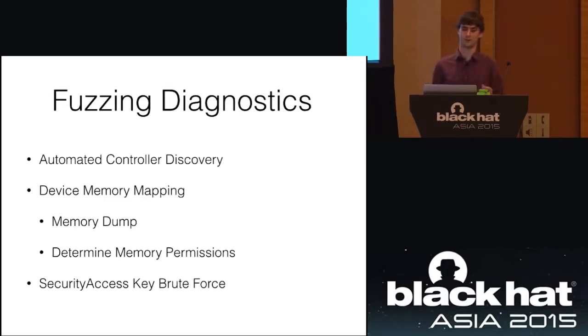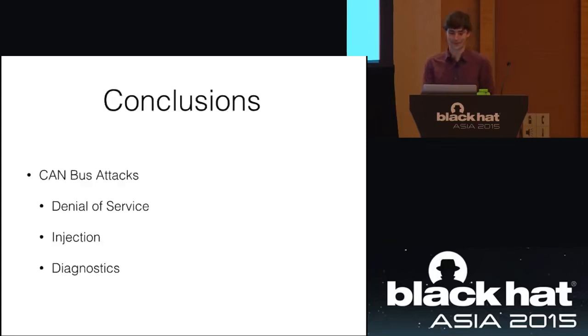So one side is we're starting to see that as we connect cars to the internet more, you get attacks like the recent BMW one where they did authentication over HTTP, and you could create a fake GSM base station and man in the middle it. But the other side is that it lets people potentially get access to these CAN buses and exposes a whole bunch of functionality that the automotive folks just never really secured. So most of the stuff in automotive security is just there and you can do it. And the reason is because they just weren't expecting anyone to try.